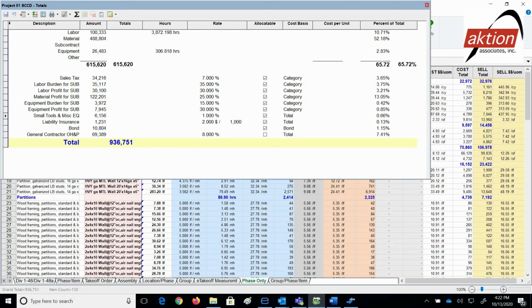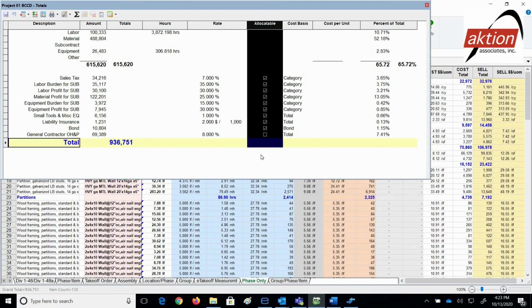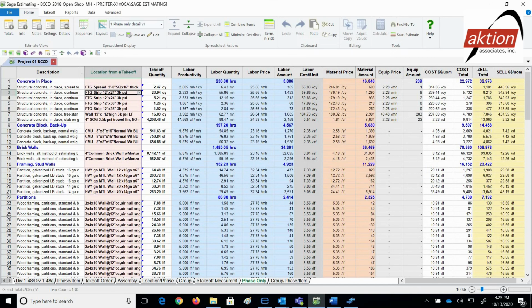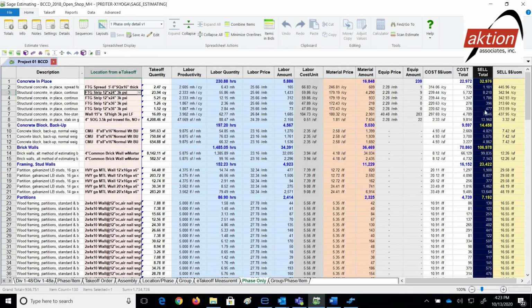It shows the cost for labor, material, and equipment. Then all you do is add your markups. We call them add-ons. As I mentioned earlier, all estimating systems estimate as if you're the sub using cost information. So all I did was add labor and equipment add-ons for burden and profit that a sub typically adds. And then those add-ons will spread or allocate into the yellow cell total column as the anticipated total that you expect from a sub. It's just that easy.